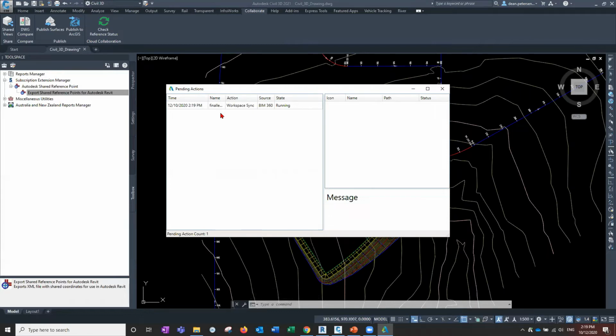It's called a DWG drawing file, but it's that plus some folders that go with it. And it's not actually a drawing file you can open. It's an intermediate translation file with the information that Revit needs to construct its terrain, but it's not actually a drawing file you can work with. So it only is accessible by this publish and then republish over the top of it.